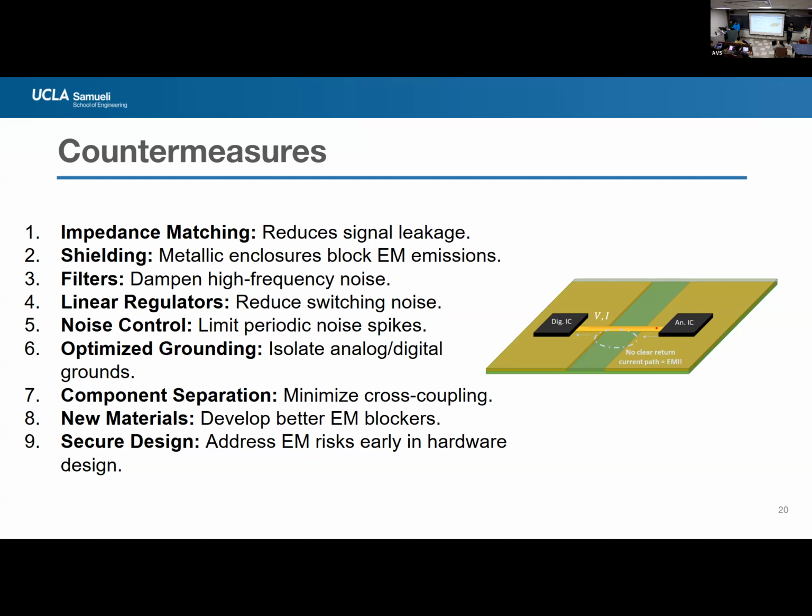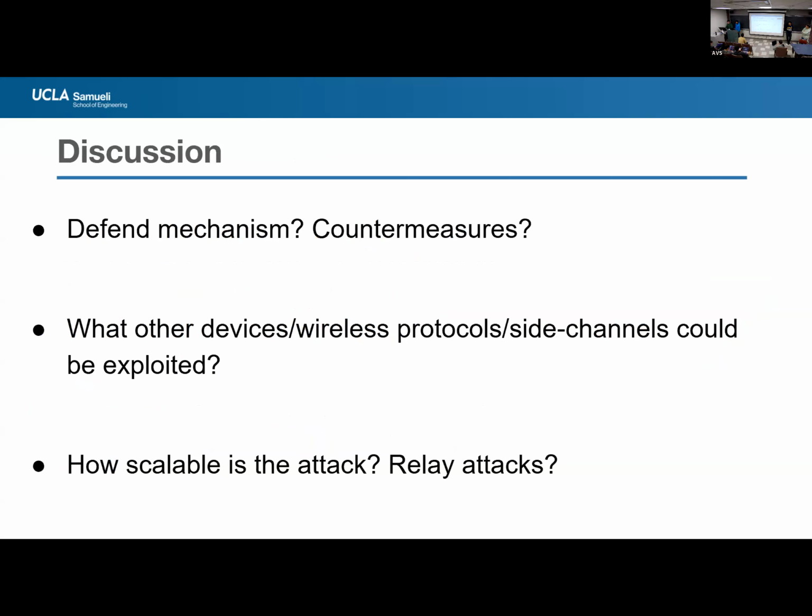So, and then other techniques that we look at is, it's important to look at how the substrate package is designed with respect to the substrate coupling, the positioning of the analog and the digital grounds, the interaction between these sensitive analog and digital components. And it's also important to look at how we can minimize noise spikes so we can have a reduction in the amount of spurs. And the solution typically to that is taking into account various switching parameters to avoid noise patterns. So these are some of the countermeasures. Most of the countermeasures can be done in the design phase of the device.